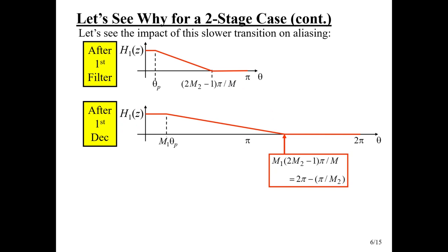Remember I'm visualizing this as a way to think about where the signal spectrum, after it runs through this filter, can be all the way out to here before it gets completely attenuated. So that part gets stretched out to there. Okay, so aliasing is going to happen.